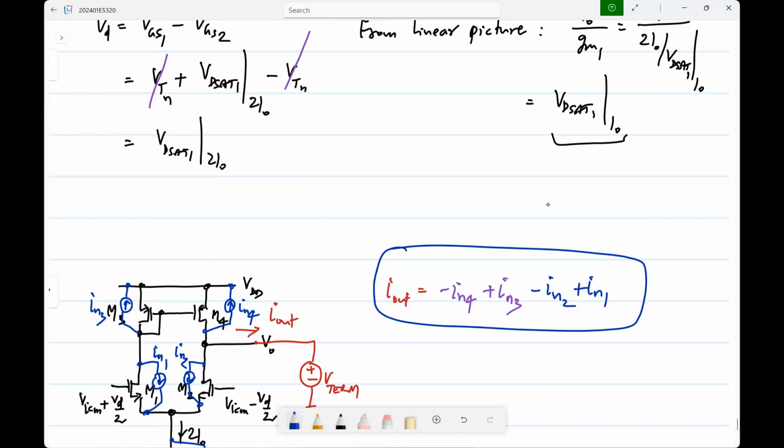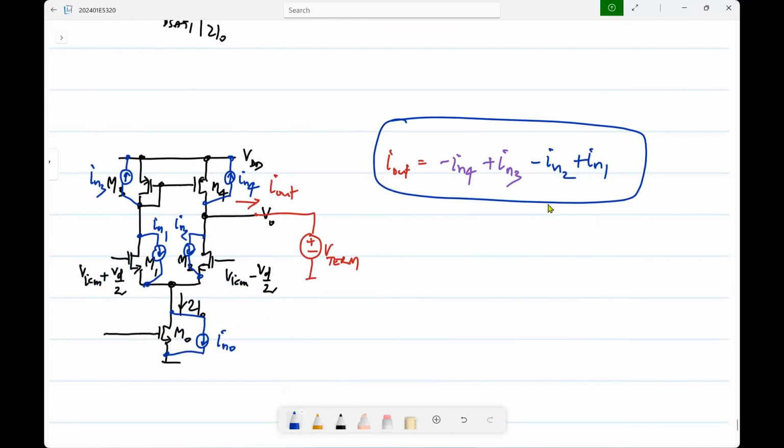Parasitic? No, this is at low frequencies. So basically, if the question is whether the parasitic admittance is negligible, at low enough frequencies you can always neglect it. So once you have this, the spectral density of the output noise will be simply the sum of spectral densities, because these are 4 different components, they are uncorrelated.